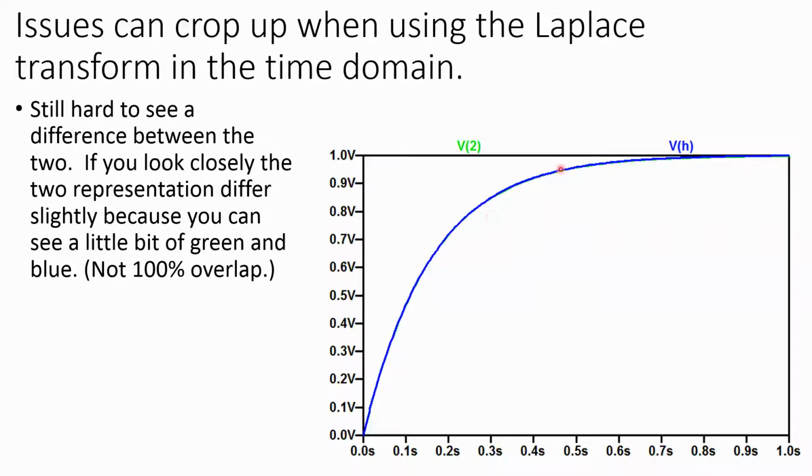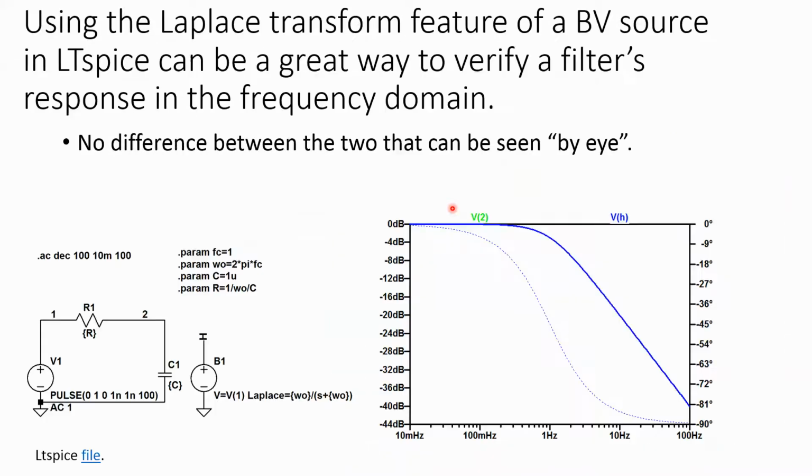If you really try, you can see a little green here, but given noise and component tolerances of a real filter, that's an insignificant difference. So for first order low pass filters, if you're exploring things, you don't really have to make an RC equivalent.